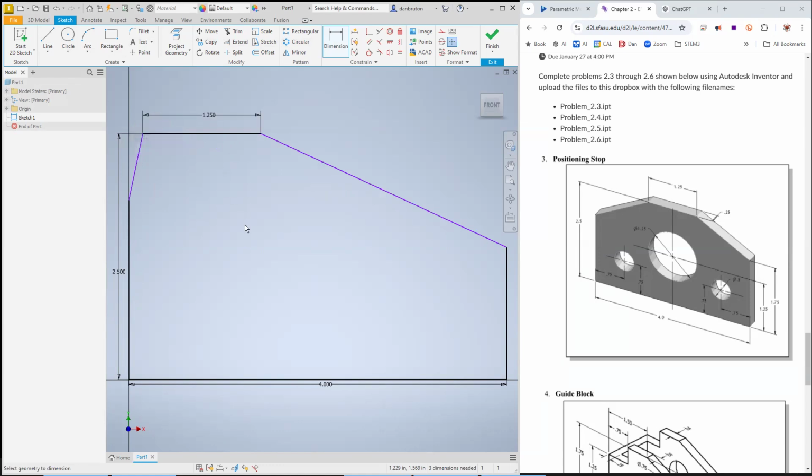And we're going to see if this is going to be a quicker way to do it. So if we click on this one, not for dimensioning, but click with Control and make those two equal. Does that help out a little bit? And it makes a mess out of it. So what we can do instead is say this one and this one need to be equal. And so the order of operations can make a difference.